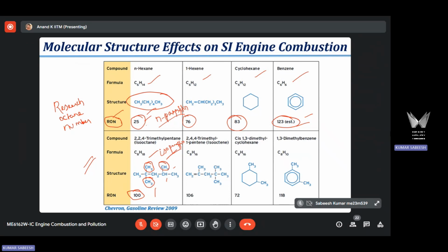Sir, hydro... you told us that if we make it react with hydrogen, it can happen. So that is hydro treatment. Hydro treatment is done to remove sulfur and nitrogen. Oh, I'm sorry, memory is misplaced. Here I'm modifying molecular structure from normal paraffin to isoparaffin, and there is a refinery process involved. In fact, they do this to improve the antiknock quality of gasoline.